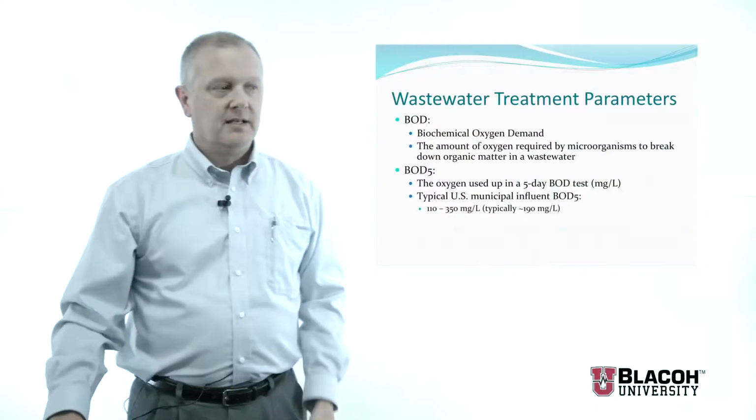We seal it tightly and we put it in a cabinet at 20 degrees centigrade for 5 days. We pull it out, we measure the dissolved oxygen concentration, we know how much oxygen was used up, and that becomes then a measure of the biodegradable organic material that was in that wastewater that we put in the bottle. Okay?